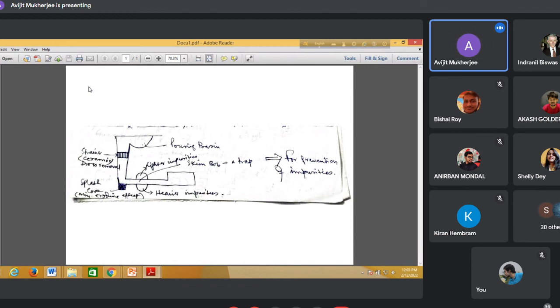Okay. So comparatively pure metal will enter in the cavity. So after pouring molten metal in this pouring basin, next is the down gate, the vertical down gate. Again, somewhere here, there is a strainer. This is ceramic material. Strainer is used to remove dross.